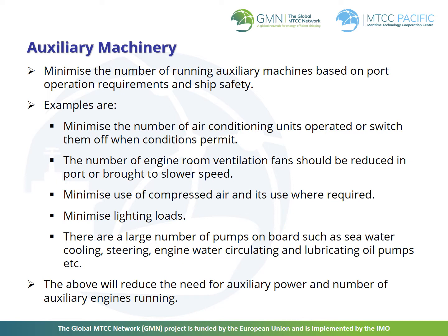Minimize the use of compressed air and its use where required. Minimize lighting loads. There are a large number of pumps on board, such as seawater cooling, steering, engine water circulating, and lubricating oil pumps. These measures will reduce the need for auxiliary power and the number of auxiliary engines running.